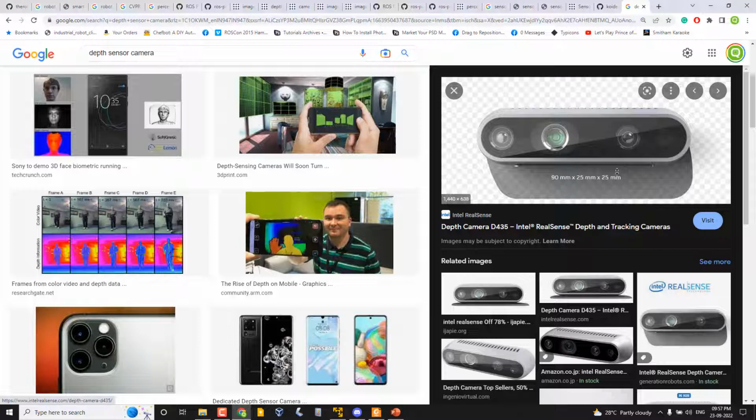Okay, in RealSense there is an option to do stereo cam as well. But before RealSense, the depth sensor like Kinect would only work indoors. The technology they have is IR projection. The IR will be projected to the environment and then it will reflect back and be collected, and the time of flight, the time of returning to the receiver, will be calculated, and the depth of each point will be calculated.